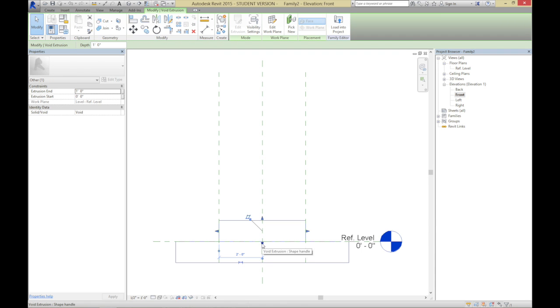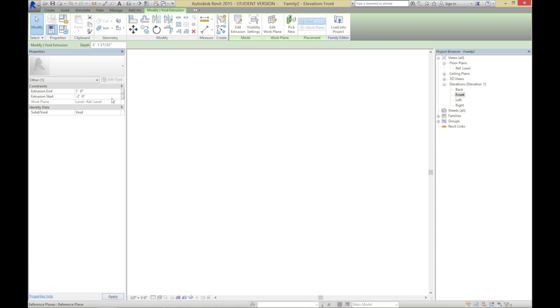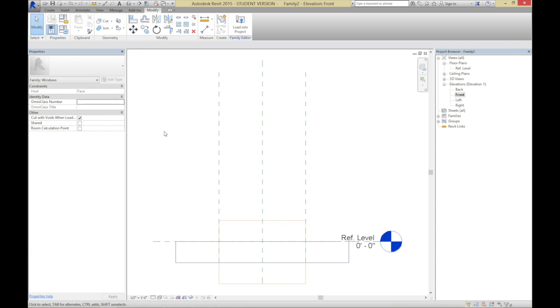Choose that, and let me just stretch that down. I'm going to stretch the void down so it'll definitely be as thick as any plane it might be put into. So maybe like -2 foot. Beautiful. Okay, and if it's only going to really be cutting from the hosting element, the plane, it's okay if it's a little bit long, it won't cut excess things out.